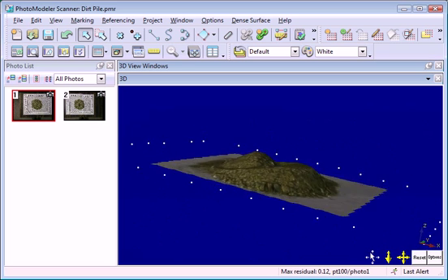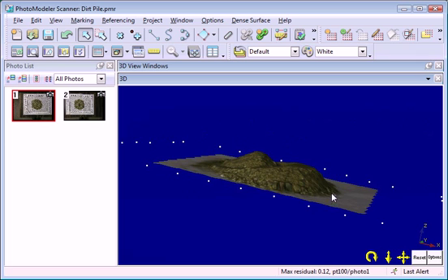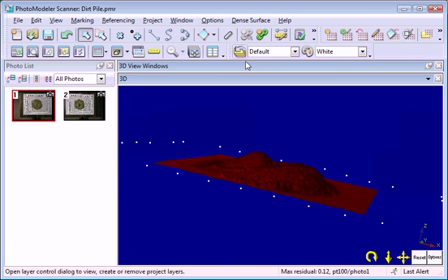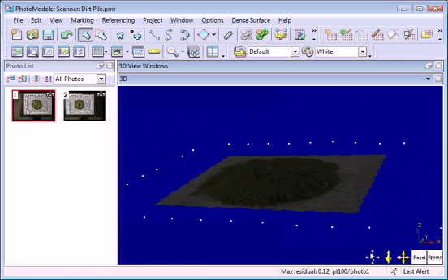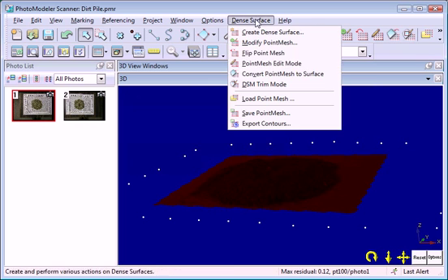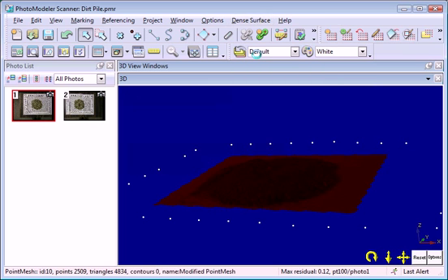The meshing steps have no way of knowing which way the resulting triangles should face. If your mesh is facing the wrong way, you can select it and use the Flip Mesh command to have it face the opposite direction. Select it and flip it back to the correct direction.